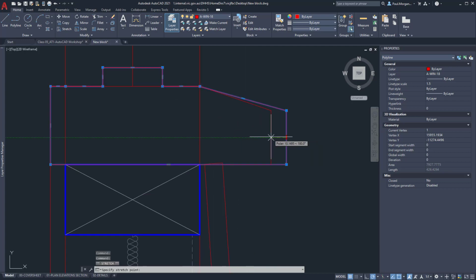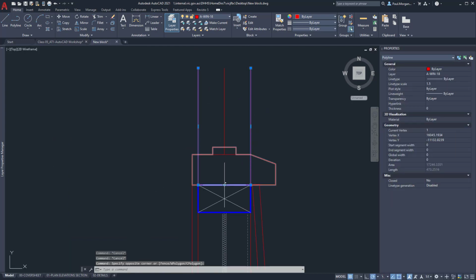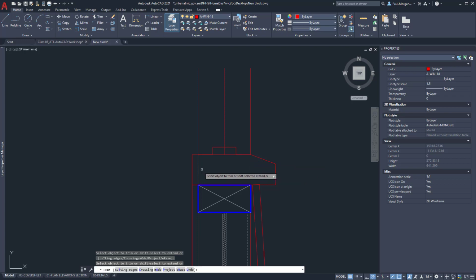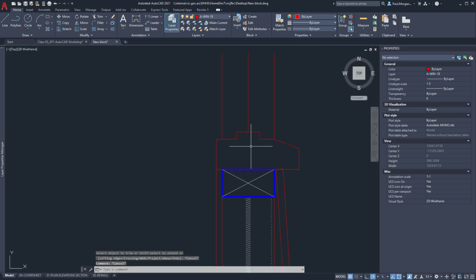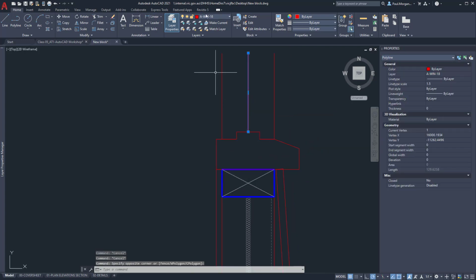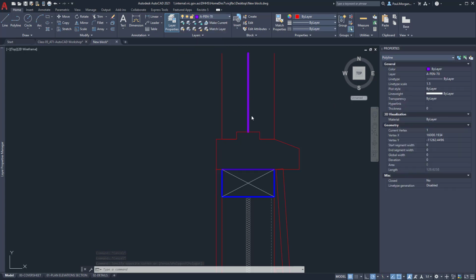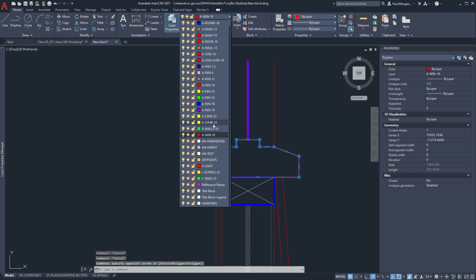And in fact, I might just bring this further back in a little bit. I'll bring that back in, say 15 mil. All right, so now what I can do is I'm going to move these polylines. Well, in fact, I am going to trim those polylines to be something like that. So there's my glazing line. My glazing line I'm going to make much thicker. I'll make that, say, a pen 70. I'm going to up this to a pen 35.